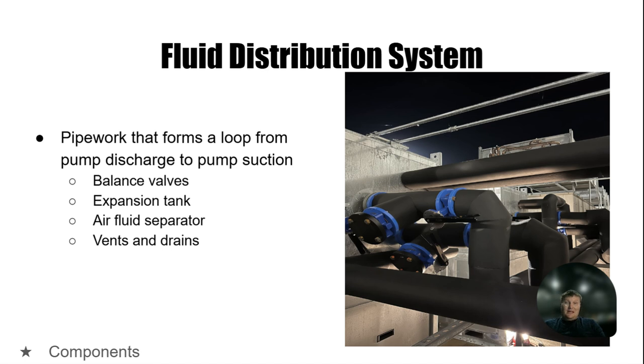Most of what we're doing is brazed with silver solder, and then we use soft solder on all brass to copper fittings and potentially nearby. One thing to be mindful of is if you're moving these pipes around, you have to be careful near valves because soft solder cracks really easily, and you don't want to have a bad day if one of those cracks or breaks off.